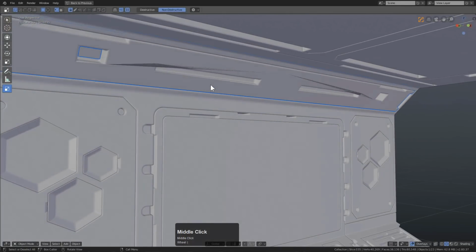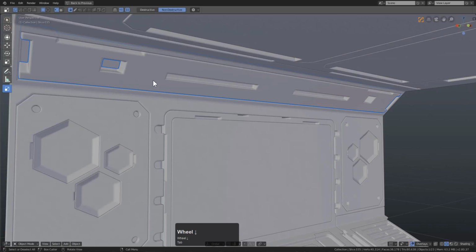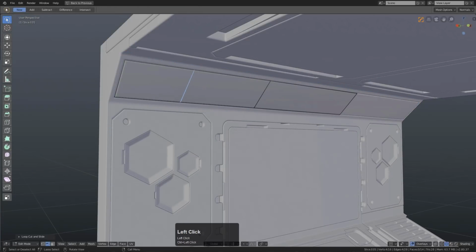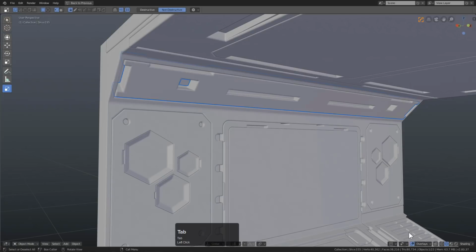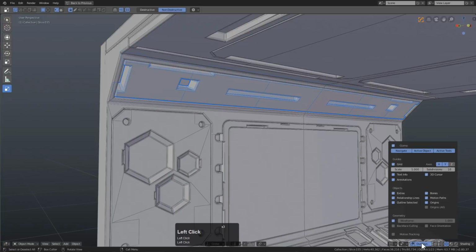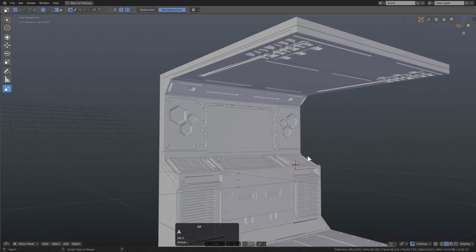So I just kind of got used to this plane. It's a friend. Right there, just put a loop cut in edit mode. No need to even summon a blue box. No need to even change my tool. Just put a quick cut there, just an edge to help it out. Help a Boolean out. Just give a Boolean an edge, you guys.